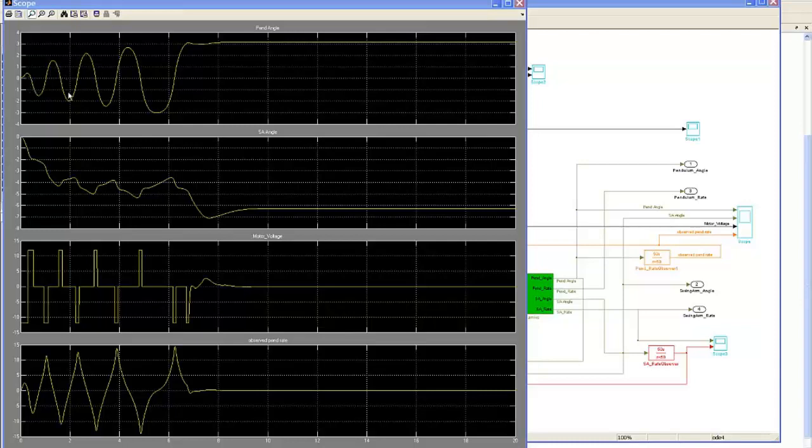It then gradually adds energy to the system by sending these motor pulses at the appropriate time. Once the pendulum gets close to pi radians, the controller transitions from the swing up mode to the hold mode and then rapidly stabilizes the pendulum at the vertical position.